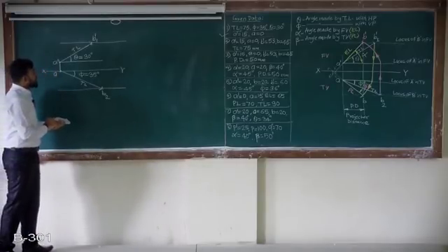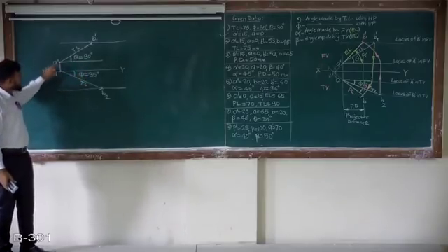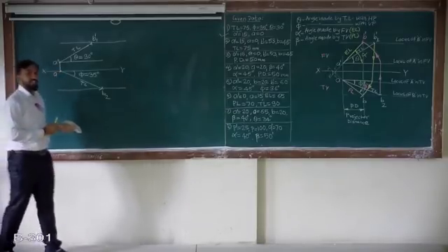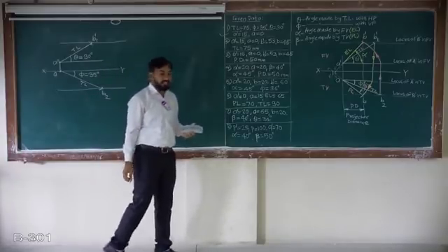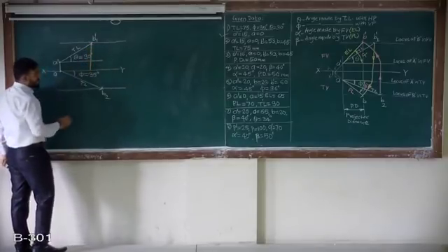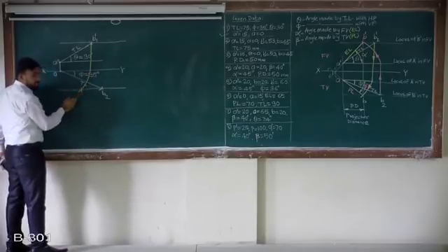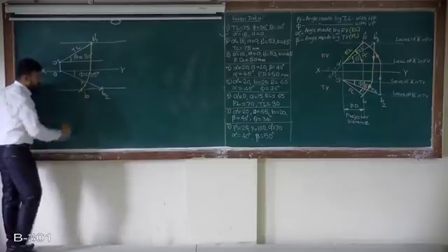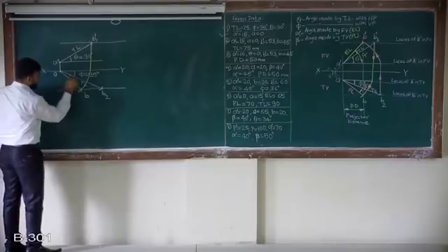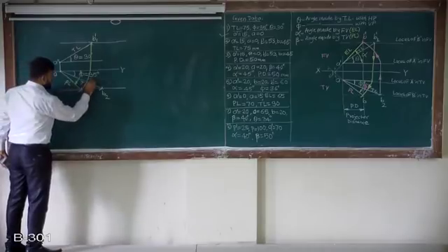Now I know 5 parameters. I just plotted this A dash, A, theta, phi and the true length. So that is the complete given data. Now I need to find out apparent length and apparent angles. So how can I find this? I'll project this B1 dash onto the locus of A and then rotate it on the locus of B. I will get this point as point B. Join, this is plan length, and this angle made by this PL is called beta.